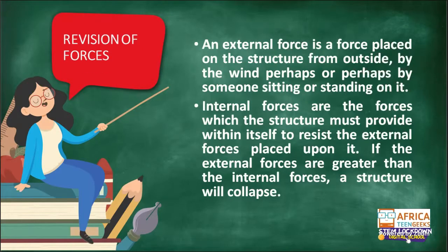An external force is a force placed on the structure from outside by the wind, perhaps, or by someone sitting or standing on it. So we also have internal and external forces. Internal forces are the forces which the structure must provide within itself to resist the external forces placed upon it.